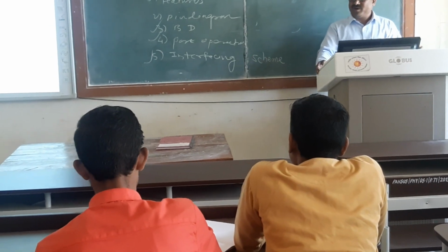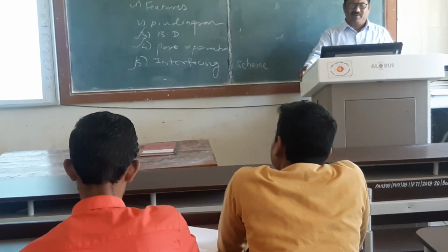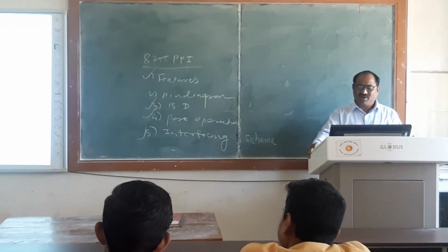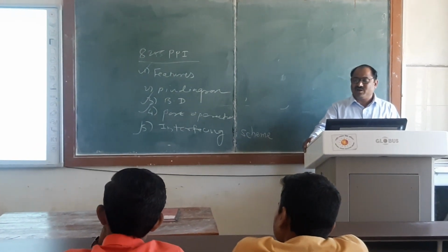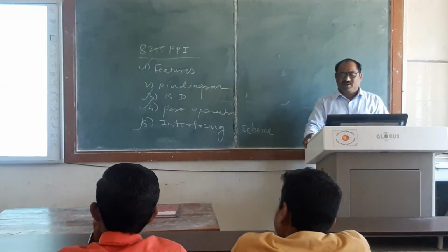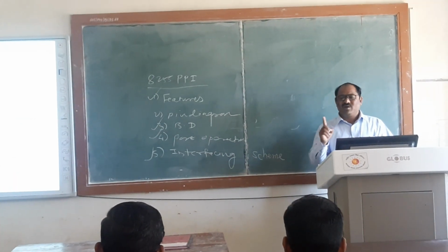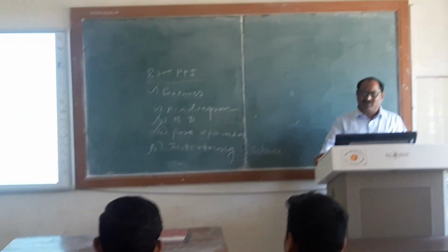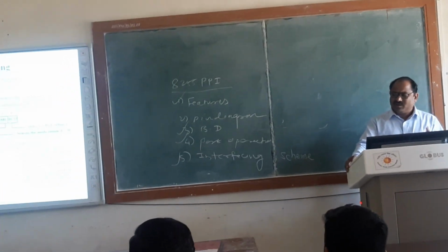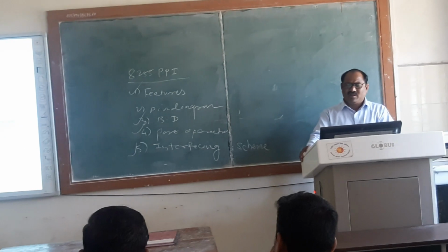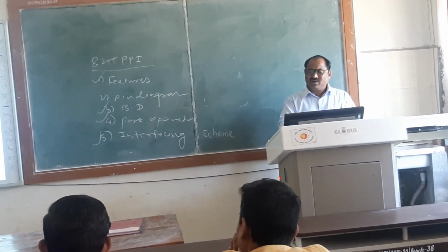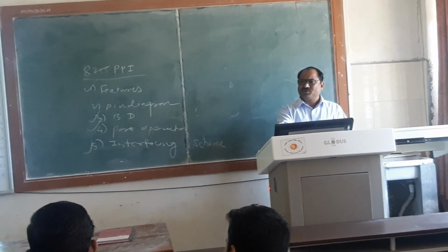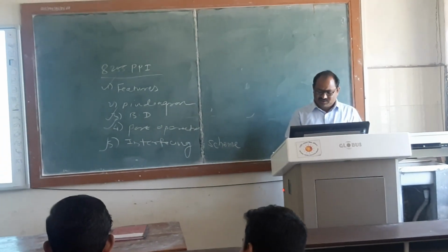For example, just see, if D6 bit equals 0 and D7 bit equals 0, then counter 0 is selected. Then for 8254, the BCD bit is equal to 0. And after that M0, M1, these are the modes. So in the modes, for example, if it is 0, 0, 0, that is mode 0. So we will see this.